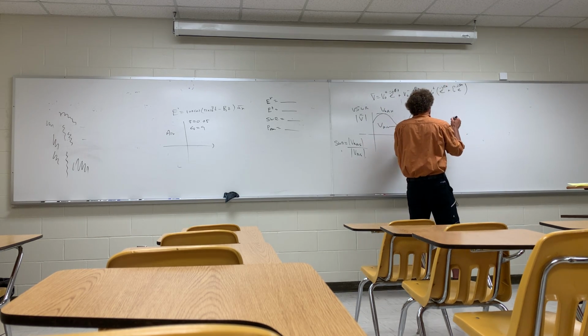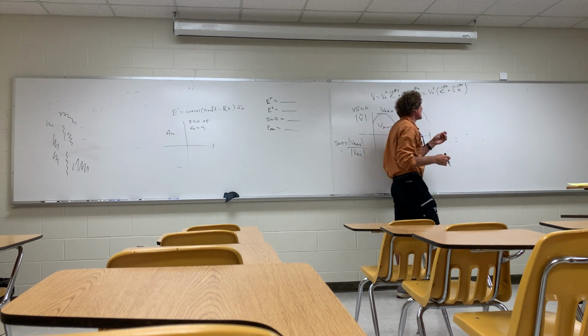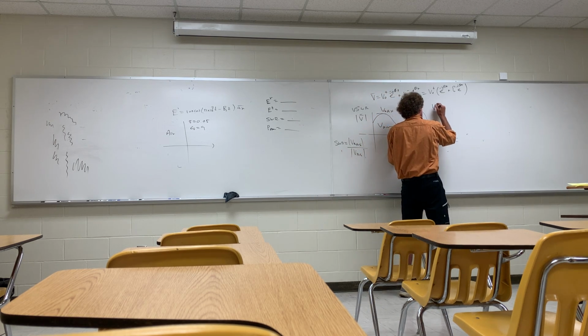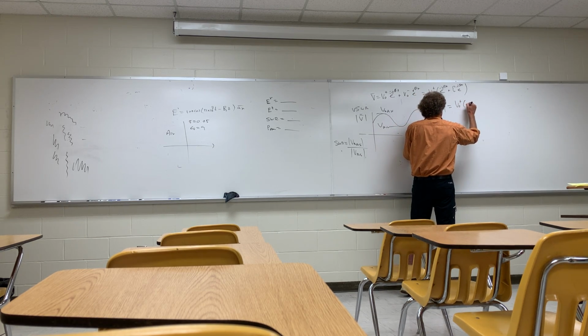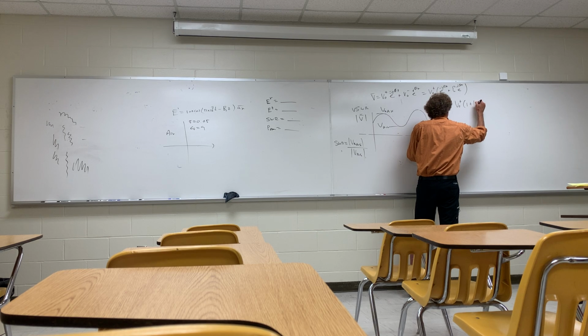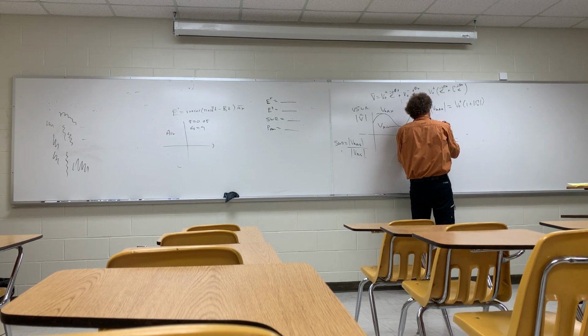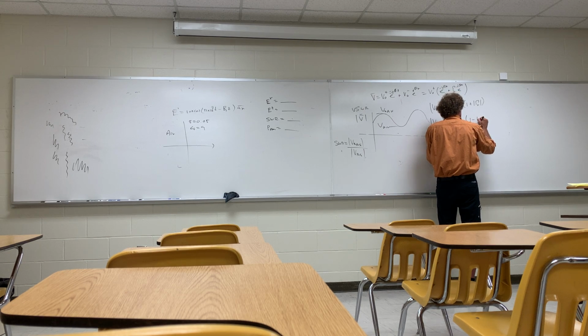And for the standing wave ratio, you remember how to get the maximum of this? What is V max, the maximum possible magnitude? That's simply V0 plus times 1 plus the magnitude of gamma. And V min is V0 plus times 1 minus the magnitude of gamma, because gamma could be complex.